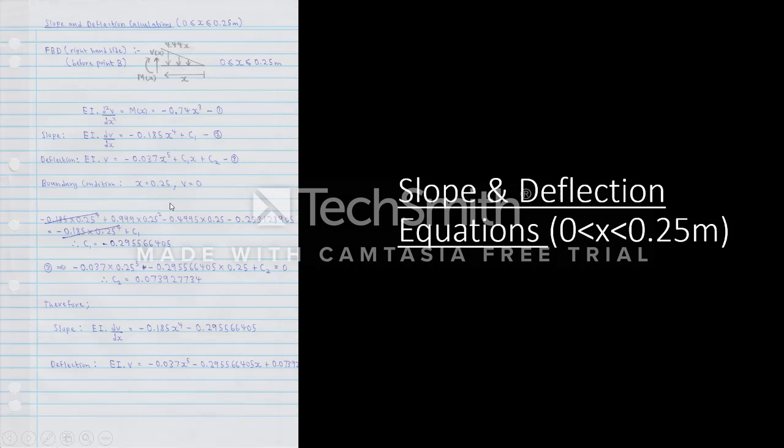And also the moment of inertia, which is this number right here. Thereafter, I found out the maximum deflection is this number right here. I did the same method and found out the slope and deflection equations for the range 0 to 0.25 meters. It's the same integration and also the finding of the constants using the boundary conditions.